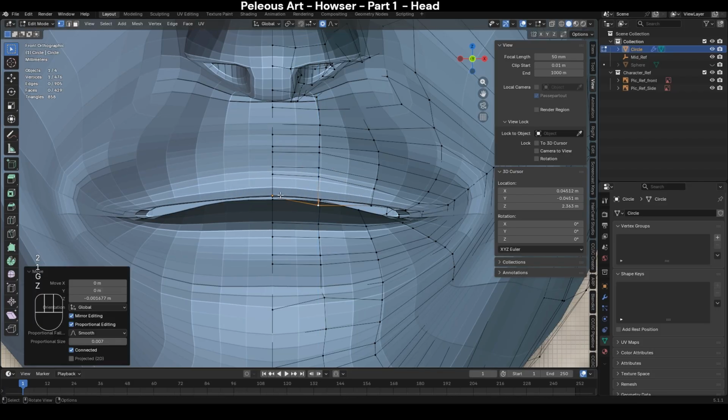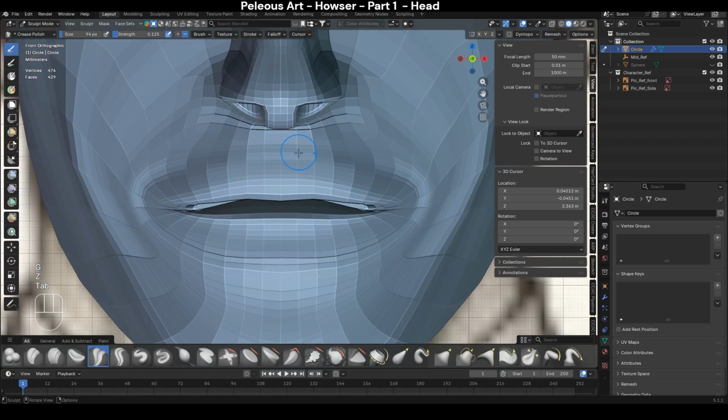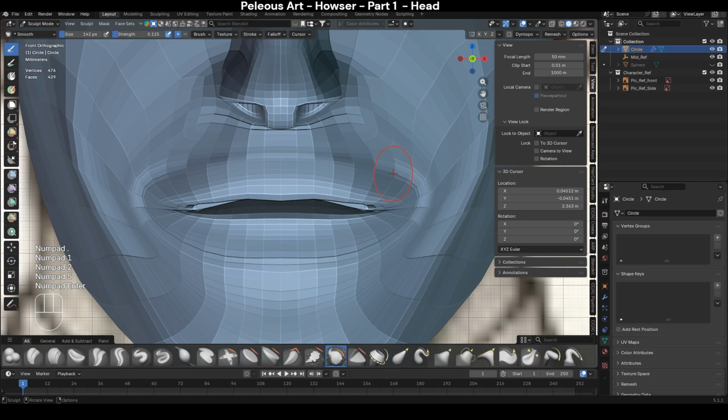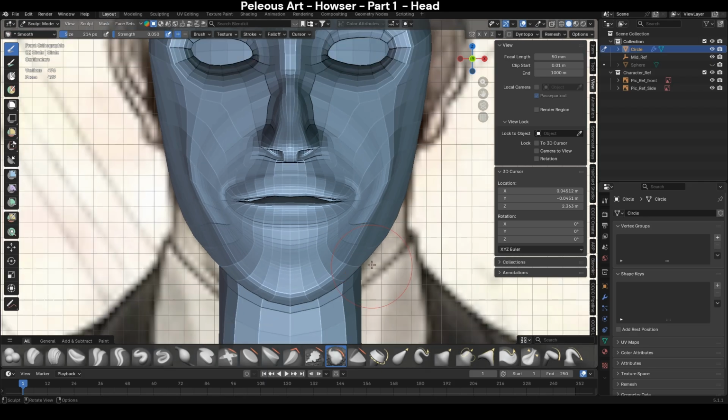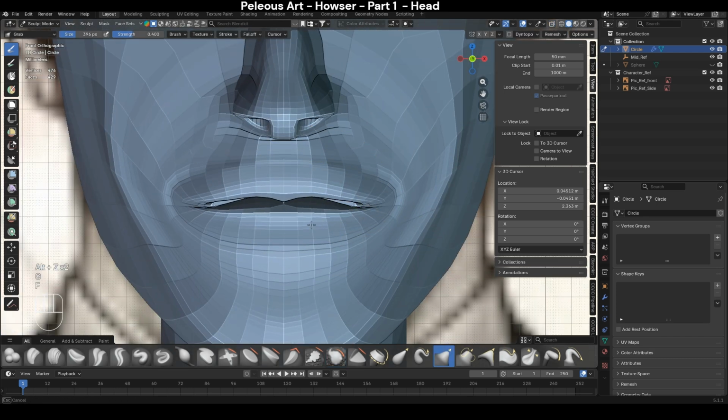Let's select those vertices and pull them down as the lips seem closed from outside. Now can we crease? Okay, great. Let's crease and smooth a little bit on the edges of the lips. We have enough faces to do that. Okay, very gently with low strength on the smooth tool, so we don't smooth it too much. Just match it with the reference.